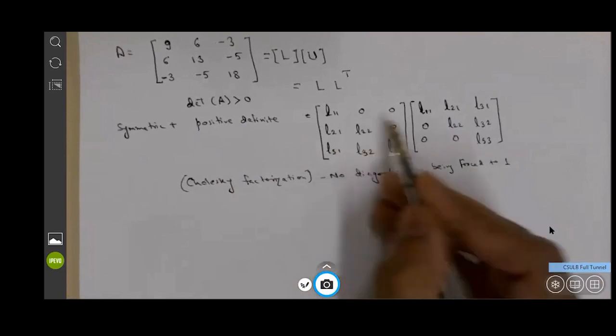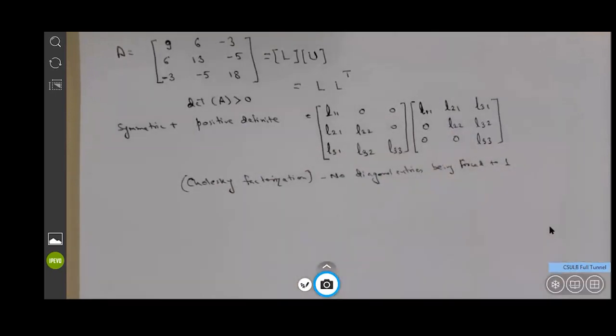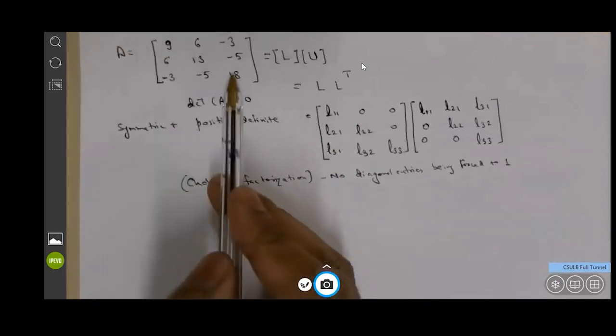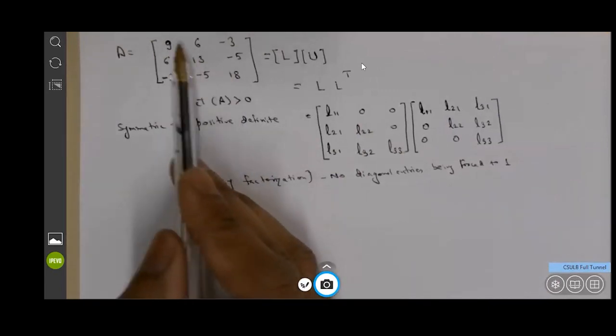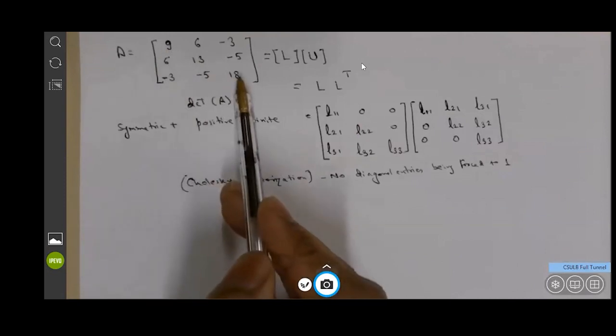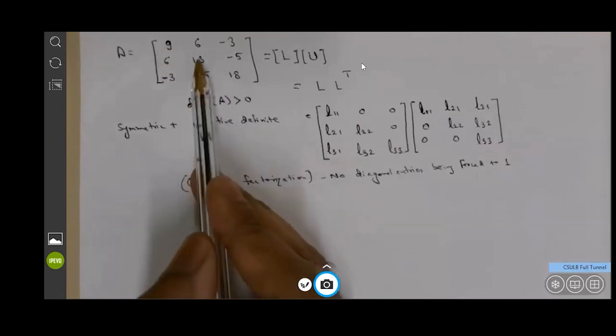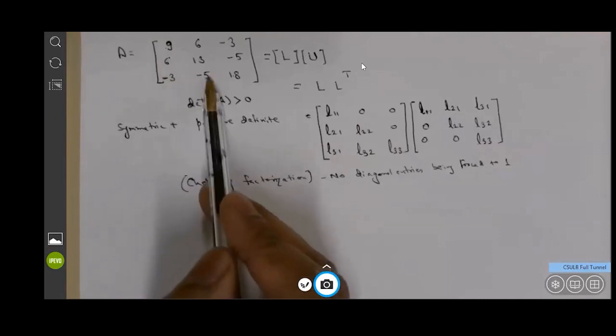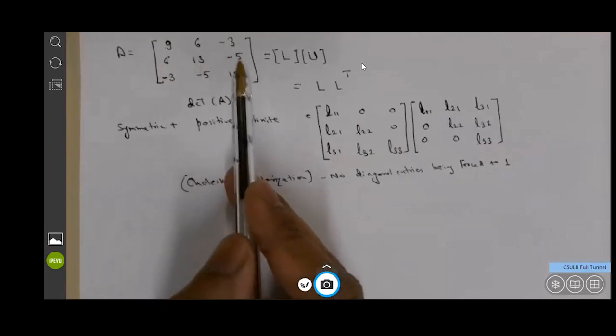So if I have to find these coefficients, what's happening? What is the problem here? Or what is the scenario? Okay, so Kyle says because it is symmetric, we can eliminate 3 values, which is perfect. That's what it is. So if you look at this, this is a symmetric matrix. So it actually has only 6 independent numbers. It has got diagonal numbers 1, 2, and 3, and 4, 5, and 6. The other 3 values are just the same.